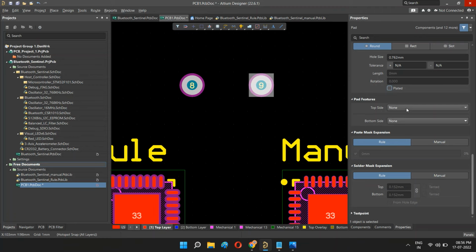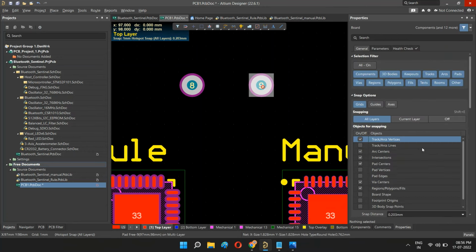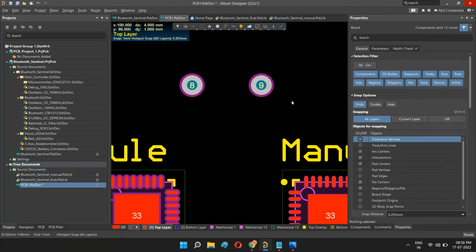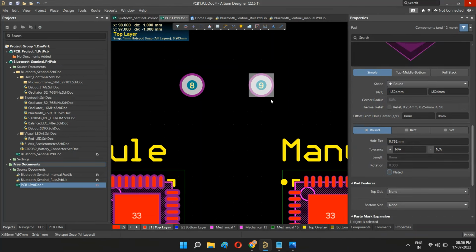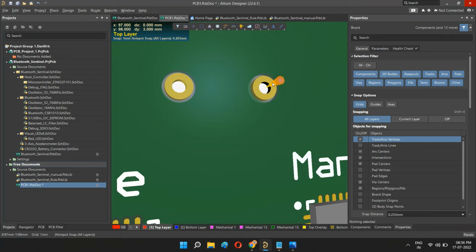Usually what happens when we create a footprint, we see here it is plated, right? Here they haven't mentioned it is non-plated. So we think, okay, we created a footprint based on this plated rule. It is not non-plated. Here it is clearly mentioned, right? It is plated. But sometimes we forget to check this. When you check this, then only it will become plated. Otherwise, it remains non-plated only. So always remember this error. In 3D you may not always detect this error.